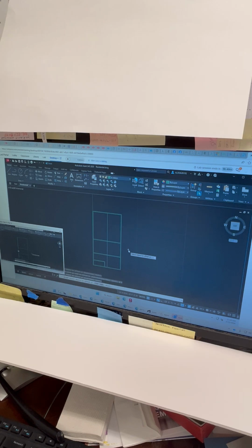8'3". Anytime you enter in a distance, you hit enter on your keyboard, and then you're going to select that resulting line and offset it anywhere to the right, 3.5, which is your default distance. Just go ahead, 3.5. All right, now you can hit enter to exit out of the command. So this is what you're left with.